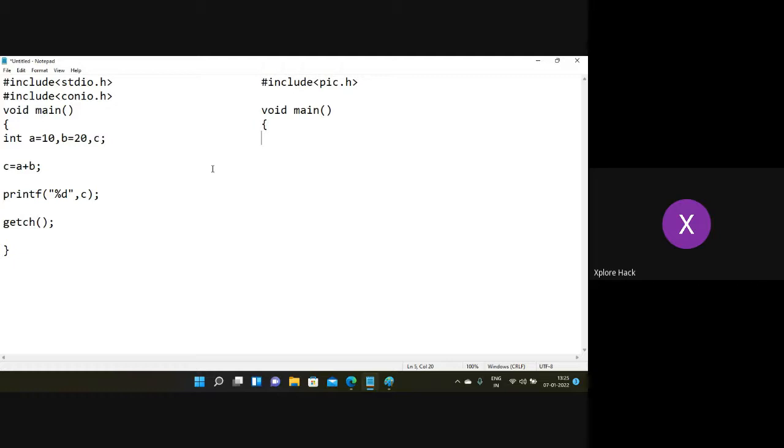Okay, so here you need to configure the pin, or change the state of the pin, to output if you are connecting any output based devices to that specific pin. You need to configure the pin as input if you are connecting any input based devices. As I told you before, you can use a switch as an input, and an LED can act as an output device, or a 7 segment display can also be described as an output device, and an LCD, and other kinds of hardware devices you can configure as output devices, and a button can be an input device.